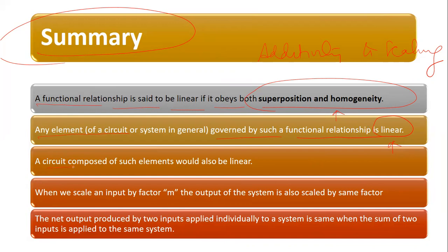Now, any circuit which is composed of linear elements is a linear circuit, right? Okay, when we scale an input by a factor m, the output of the system is also scaled by the same factor. This is what scaling, or homogeneity, is.